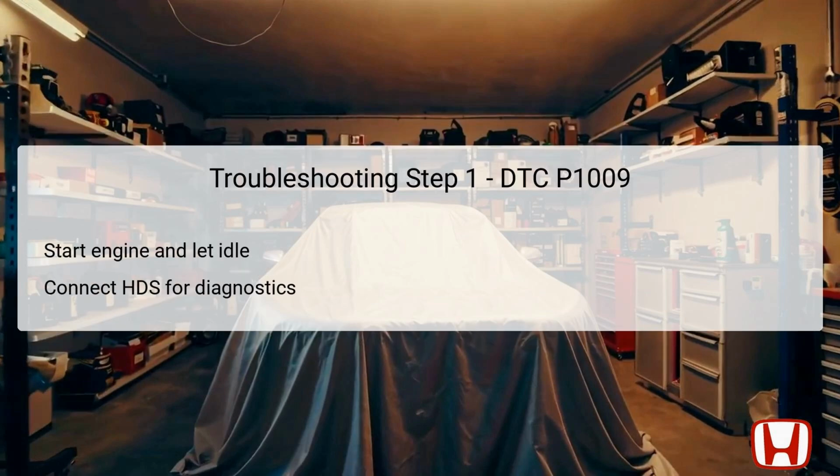The first troubleshooting step involves starting the engine and allowing it to idle, which is crucial for establishing baseline conditions for diagnosis. It's important that the engine is warmed up, as certain variables may affect the VTC's response. After starting, you will connect the Honda Diagnostics System, or HDS, which allows you to access the vehicle's onboard diagnostics.